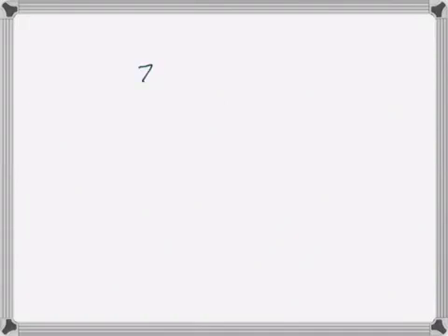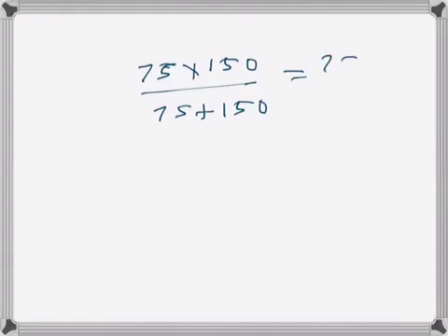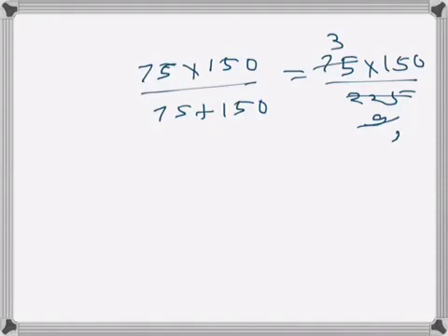So we have to find the equivalent resistance of these two, 75 kilo ohms and 150 kilo ohms. That will be 75 times 150 divided by 75 plus 150, the equivalent of two parallel resistances. That will be 75 times 150 divided by 225, so that's 9 here, and then 3 here, and then if we divide by 3, that becomes 50, so that's 50 kilo ohms. That's the new resistance now.